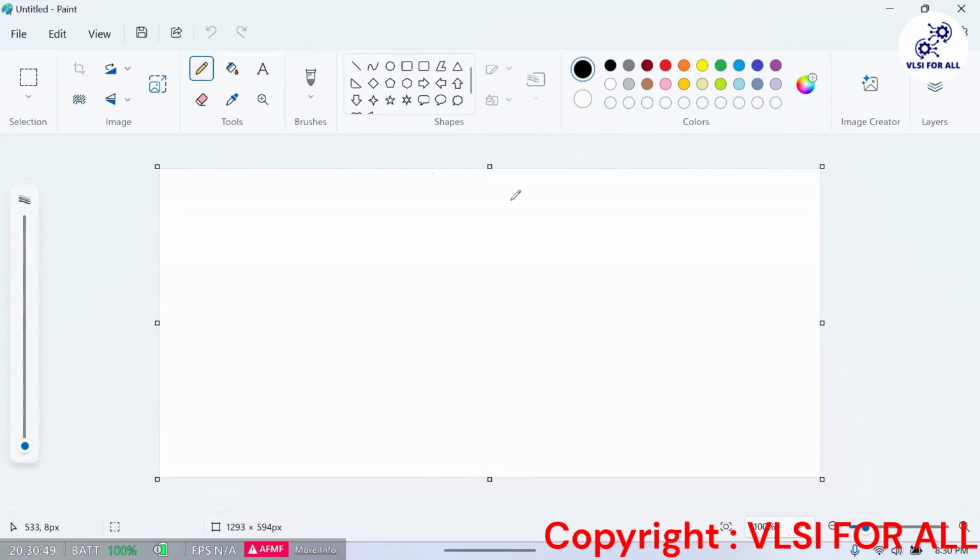So what is a voltage divider? Simple. A voltage divider is nothing but two resistors in a series combination. Both resistors, one point is shorted. Okay, it is a series connection. Then one end of the resistor will be connected to VDD, one will be connected to the ground, and from there the voltage will be checked.